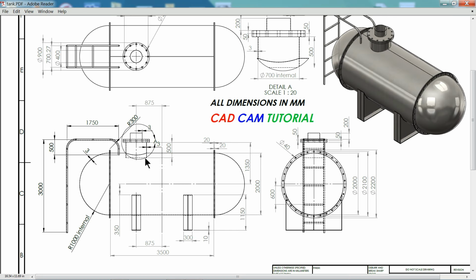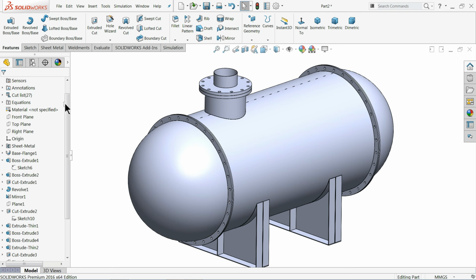Now the stand is created, the dome is also created. Now what else remains? This pipe. You see the length is 3000 millimeter by 750, height is 500 millimeter. If we look at the pipe width, the center distance is 700 millimeter. So we will create a plane at 350 millimeter. Let's see how this radius is 300 millimeter and this distance 400, but it is not shown here. I'll show you. Let me create a plane,